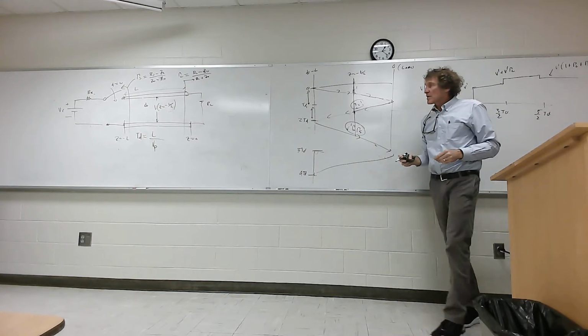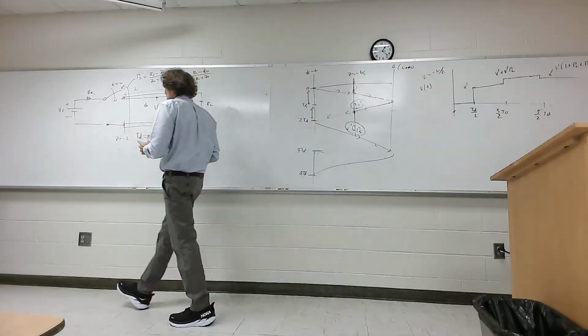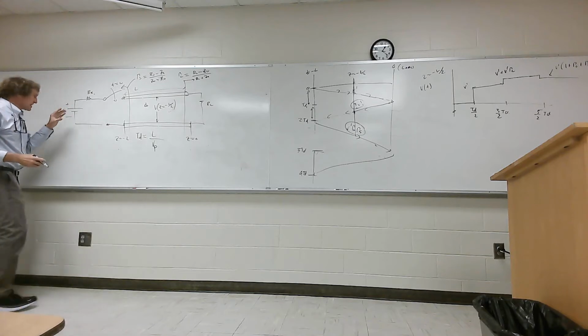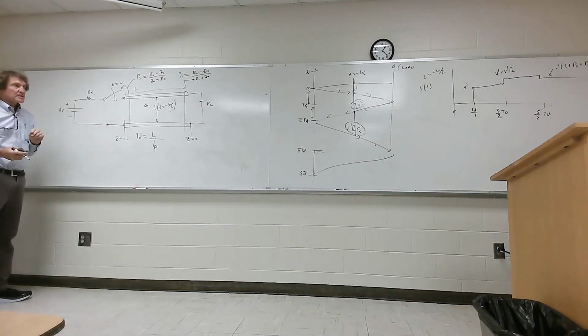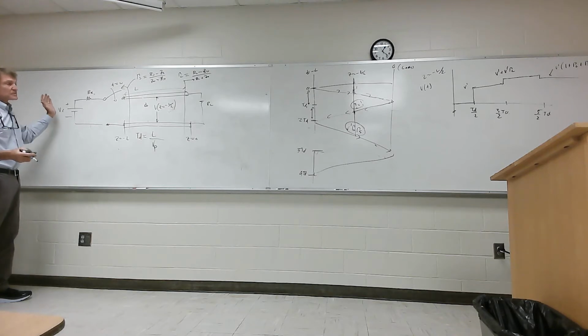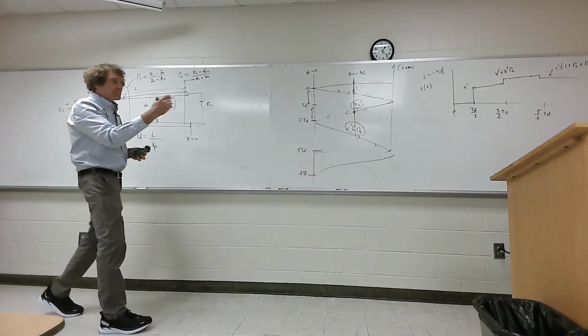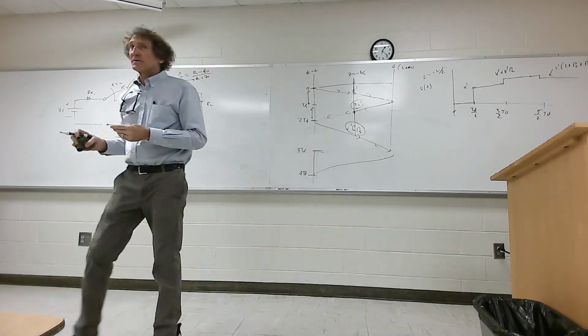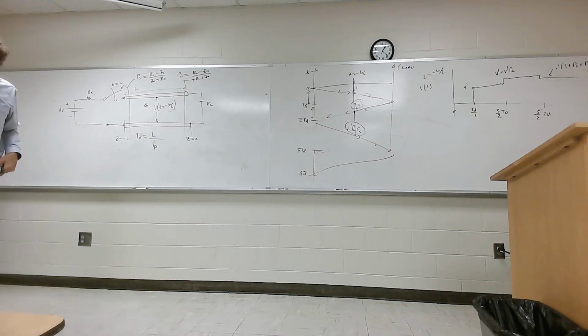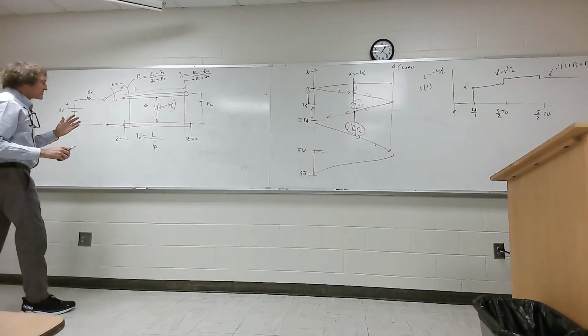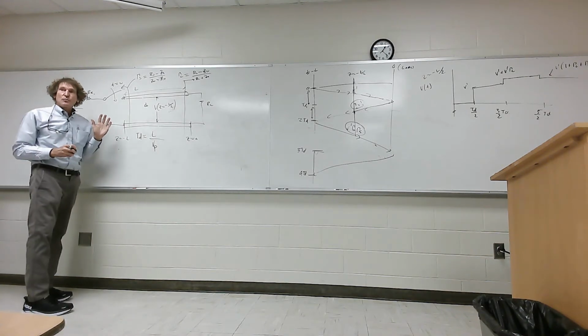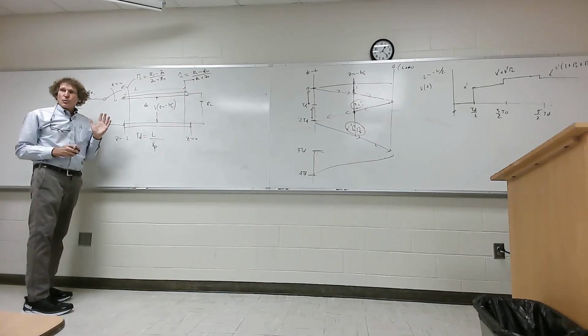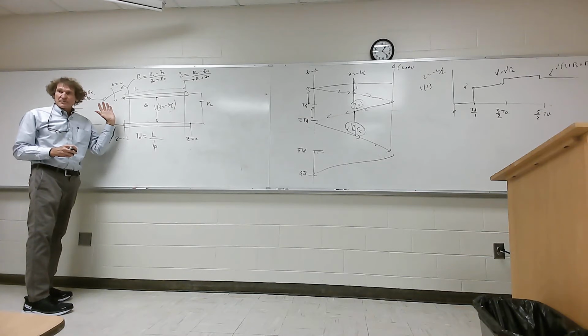Now this is something where this voltage is on there, and it's not a pulse. It's something that's staying there. A pulse would be a little different. There's a comment. Think about this now. As time goes on, and this thing's ricocheting back and forth, it's going to asymptotically approach a constant value. You all get me now? Here's a couple ways to think about this. First of all, this is acting as a transmission line when, usually, the line is greater than a tenth of a wavelength, right?